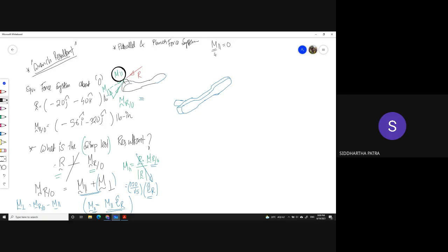That means the component of the resultant moment which is parallel to the resultant force would be 0. They were only in the perpendicular. And then we could reposition R in order to have a single force resultant. Now we can reposition R wherein I'll have a resultant force and a resultant moment acting along the same line.